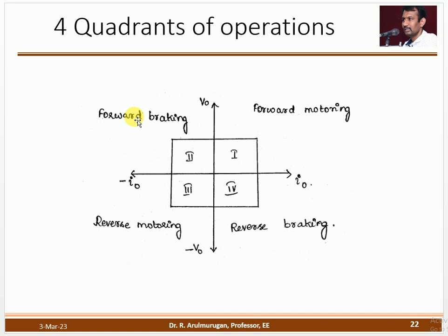So the step up converter is activated when the vehicle moves from the top of the hills to the bottom of the hills. At that time regenerative braking takes place, and only at that time it takes place. Okay, we'll come back to that.